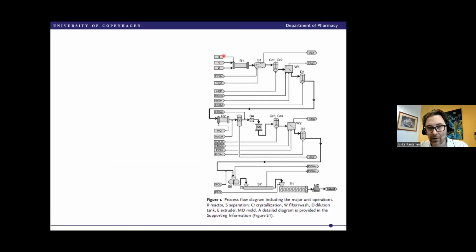But what happens here is that different types of chemistry are being handled in different steps. We have a part of the reaction happening here, then maybe some separation process here, another synthetic reaction happening stepwise, and then finally we reach some sort of roller compaction that is then extruded, and then maybe melt extruded here with the PEG, and then out comes an injection molded tablet. So the idea in their work is that they have an integrated end-to-end continuous production line.